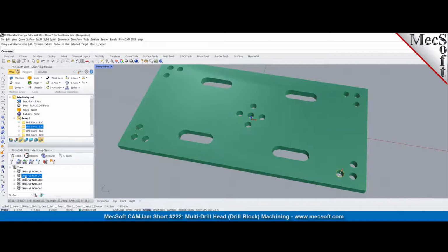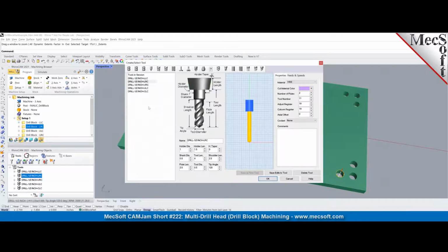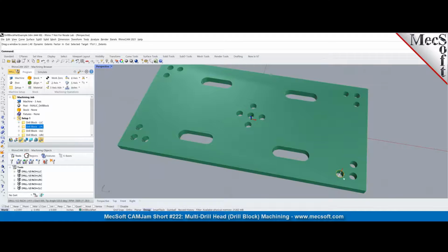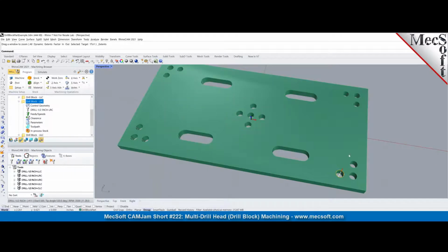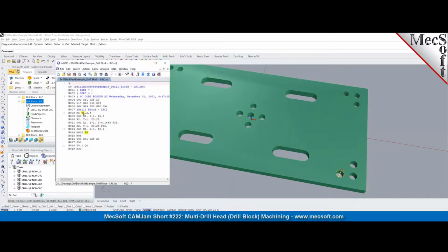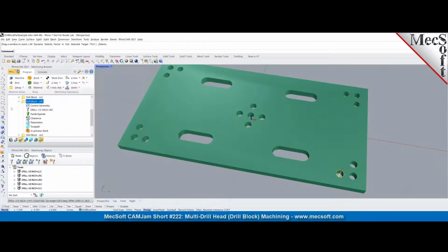So now I've already got a tool. Lower right corner, I'm calling it the LRC, and it's got 11. I got a tool number 11 encoded. And then I'm selecting this drill hole, and I've already created a drill operation with that tool selected. So when I post process this, you'll see the correct tools being turned on. So you'll see tools 1, 2, and 4 being turned on at the output level. So this is how you would program whole patterns.